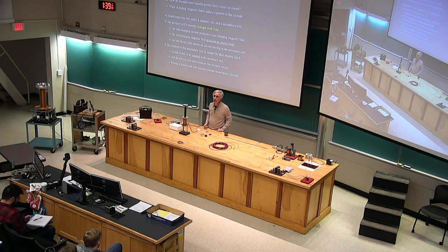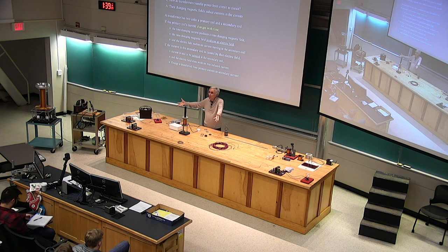This is what's known as an inductor. If I just put a wire from this point to this point and skip the coil, and I press that switch, we would blow a circuit breaker, blam, or some piece in this arrangement would explode, because there would be no consumer of electric power. I would be taking in charges at high voltage, returning them at low voltage with nothing in between that is meant to take the energy out. The inductor is serving that purpose. The inductor is taking that energy out and doing what with it? Turning it into a magnetic field.